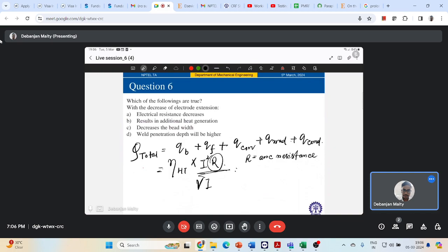Now there will be excessive melting of your electrode, and more heat input to the plates being joined, that increases distortions also. So there are different aspects of residual stress and distortion. But yes, if you're increasing welding current, there will be much more weld penetration, much more melting, and weld distortions will be very high.